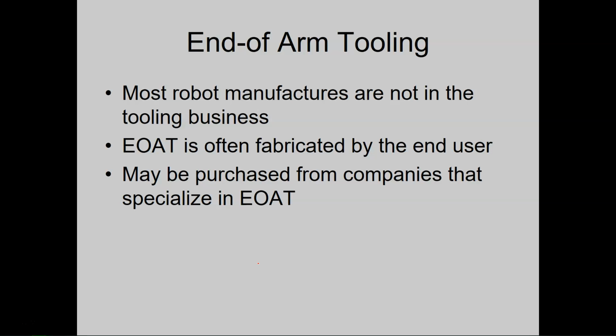If your job has a welding tool and you crash that and you tear that thing up to the point where you got to replace one, that can cost upwards of $1,000 or more, depending upon how complex the design was. That is something that a lot of programmers have to face, is whenever you are using the robot, when you're teaching it, when you're doing anything with this robot, you have to be aware of where that tool is, what orientation it is, and what is around it.